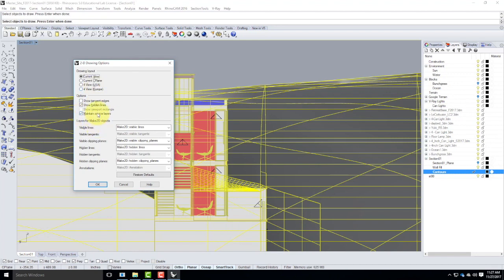I think it's better long term if you maintain the source layers, but sometimes you can run into trouble or it doesn't want to do it. The other thing that can happen is if you have too many pieces of furniture with too many hidden lines or whatever, you may decide not to show your hidden lines, which makes the Make 2D a little bit easier. So that's an option. Certainly in a section view, the hidden lines aren't quite as important as an elevation view. So I'm going to go ahead and say OK.